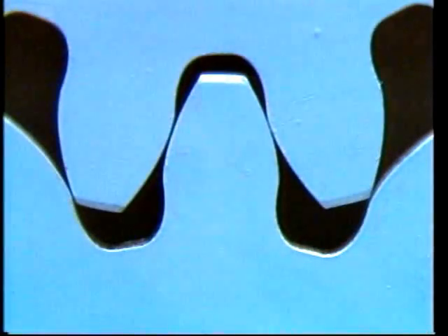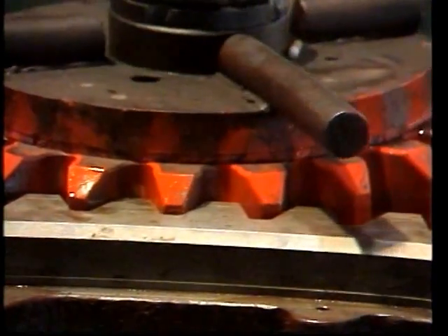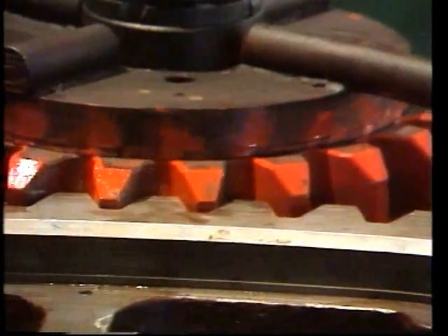The spur gear is so designed that before one tooth gets out of mesh, another tooth comes in mesh to take the load. This tooth mesh cycle provides continuous engagement, causing the motion smooth without jerk and noise.